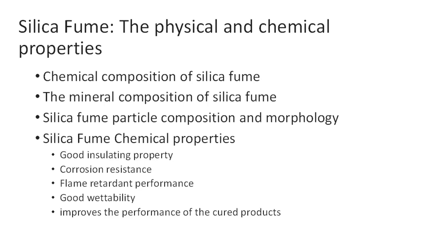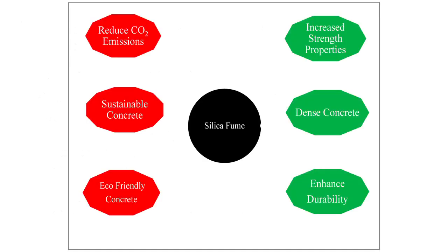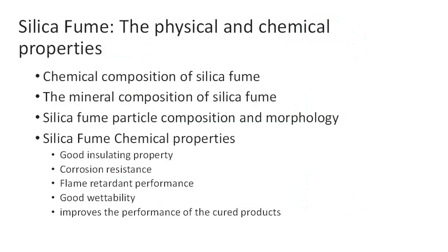While silica fume is predominantly amorphous silica, it does contain a small amount of crystalline silica, mainly in the form of quartz. The amorphous structure and the particle size contribute significantly to the high reactivity of silica fume. In some cases, high quality silica fume can have an amorphous silica content of 98% or more, making it exceptionally effective in various applications.